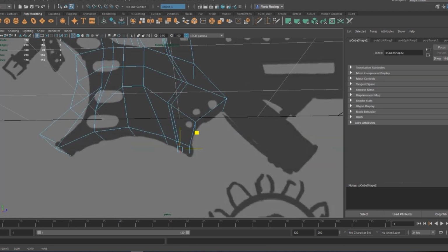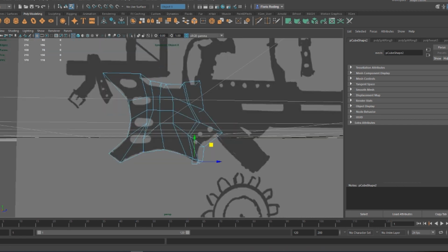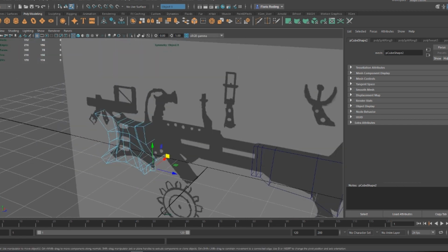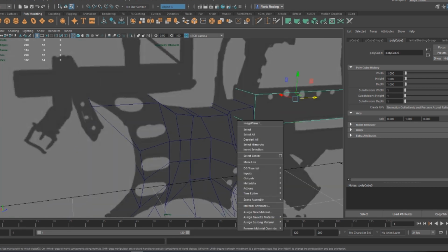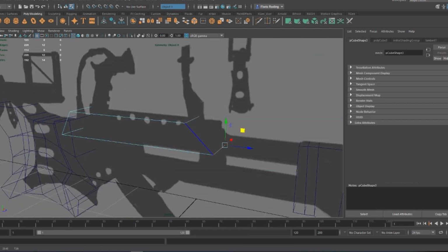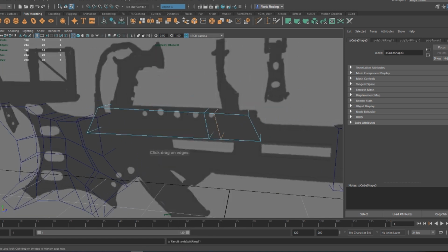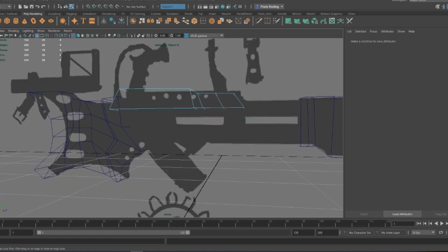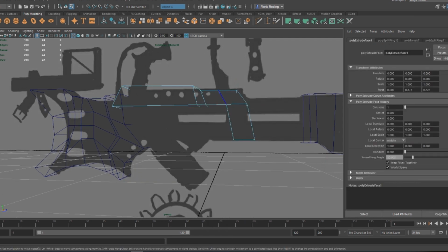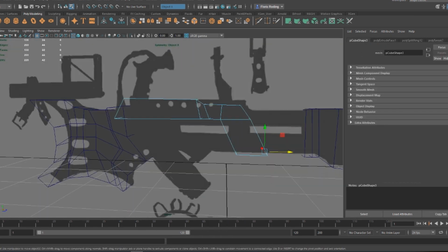Usually extrusion is a bit neater and it does give a cleaner model, but in some cases it's way easier to make two separate objects and just push them into each other. You might want to retopologize it later, but that's no problem for now. Now we just need to get the shape set up as soon as possible.